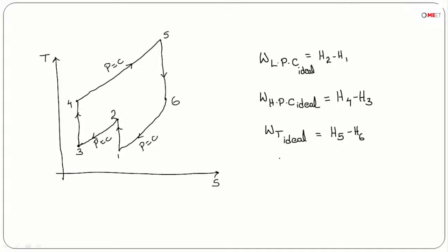Now here, as I told you earlier, as we are using two compressors, the overall pressure ratio is increasing. As a result of the overall pressure ratio increase, there will be an increase in the gross work output compared to that of the Brayton cycle. The gross work output increases, but as we are using two compressors in order to get a higher pressure ratio, the net work output may be slightly more than the Brayton cycle, but the heat supplied is increasing compared to the Brayton cycle.